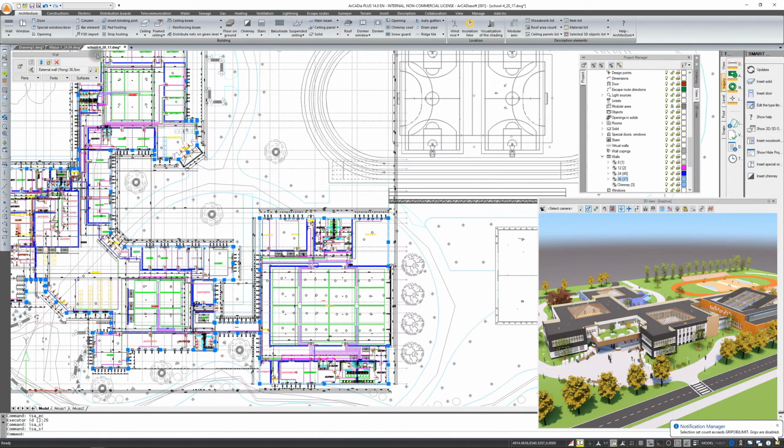This applies not only to walls, it applies to, for example, rooms, where you can sort them into groups and later it will be reflected in the list. You can also do it in, for example, 3D objects. You can do it with windows, where we will put the windows in one group and balcony doors in another group. So such groups will help you in working on the project.